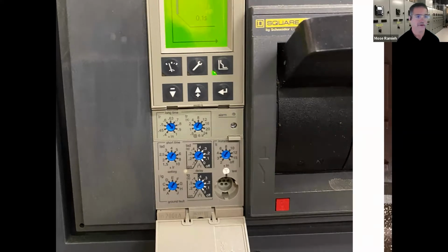And one of them is, this is a picture of a breaker I took recently where it had been in service for probably more than a year. And they were having some nuisance trips. Once again, they weren't having arc flash issues, but they were having nuisance trips. And so we got called in to investigate that. And what we found, and I can point it out here with my pointer, hopefully everybody can see this, this ground fault setting is set to A, and without going into a lot of detail, A is the minimum setting. And on this particular breaker, that is probably only a few hundred amps of imbalance. And once again, was causing that nuisance tripping.